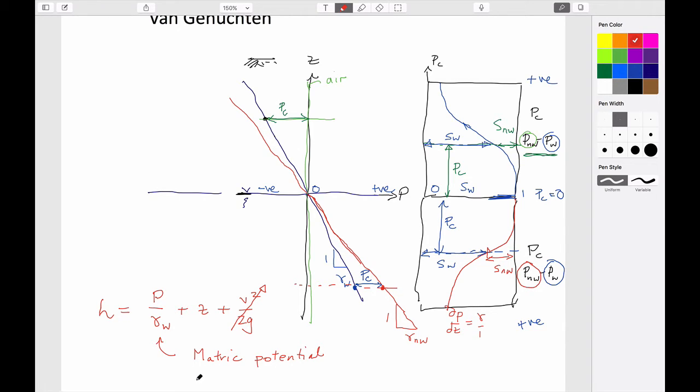And so unit weight of water typically for air, water, saturated systems, and the fluid pressure actually in the water. It could be the capillary pressure, but it could be either. I mean, the reality is that because the pressure in the air is constant everywhere, it doesn't change because of the unit weight of air, so it's close to zero. It's the pressure in the water. Otherwise, it doesn't work out.